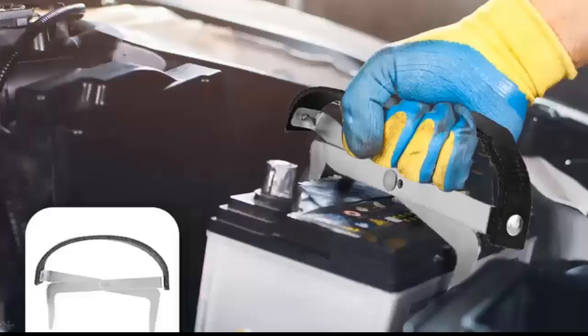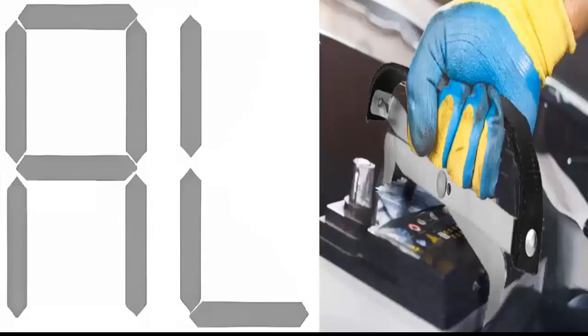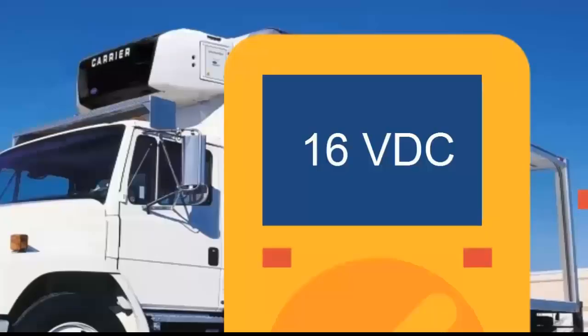6. Excessive battery voltage. This fault is identified with code AL5 and occurs when the voltage is too high, potentially damaging electrical components. It is recommended to check the voltage regulator and alternator using a multimeter.